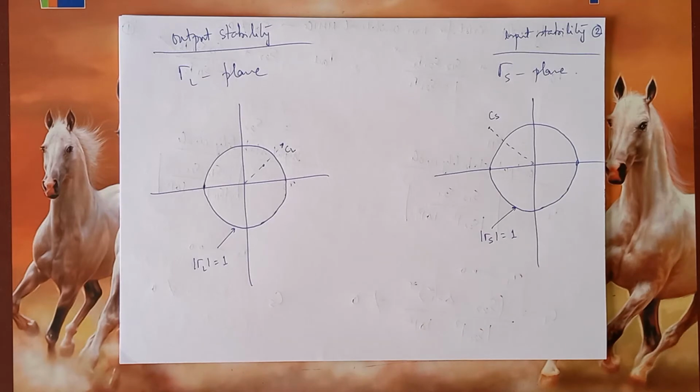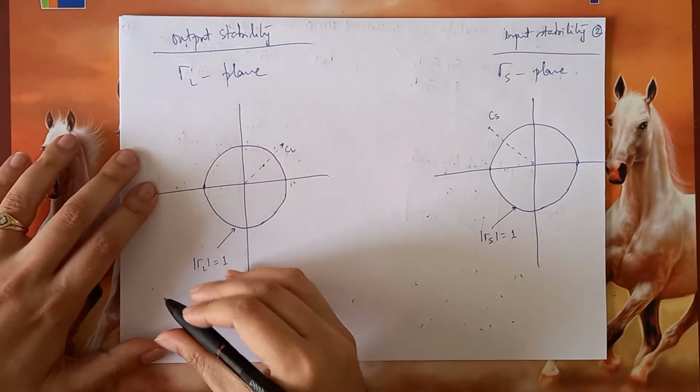So what we see is that ideally we expect any MMIC amplifier to have S12 0, and that also simplifies the calculations a lot. But from the stability angle, it may not give the designer too much flexibility. So it is always good that we have some amount of S12 that is non-zero.